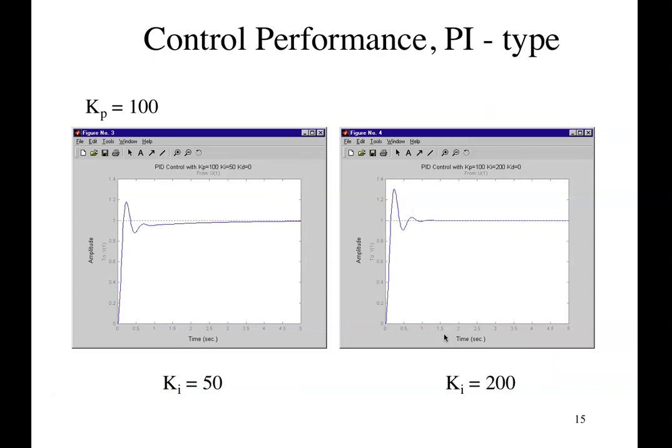It is possible for many systems that you only use these two terms, with a proper tuning of proportional gain and integral gain, to give you a good response time, no steady state error, and reasonable overshoot. And as the one you can see there, it settles quite well as well. The rise time is not too bad. But sometimes if you do have problems with overshoot